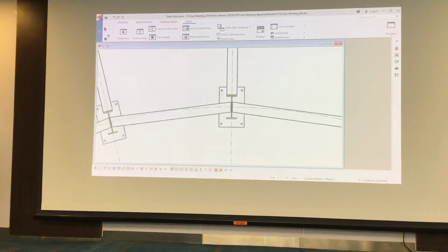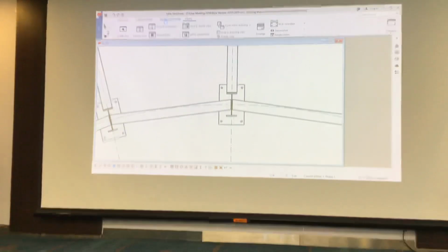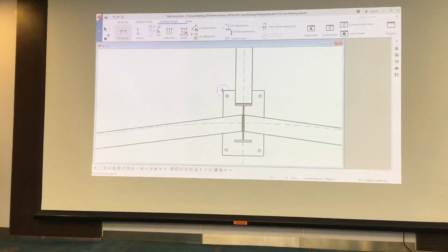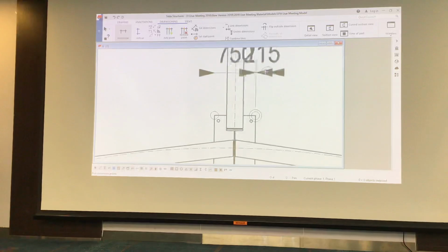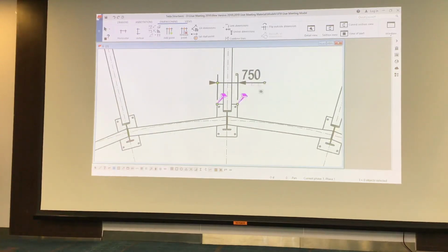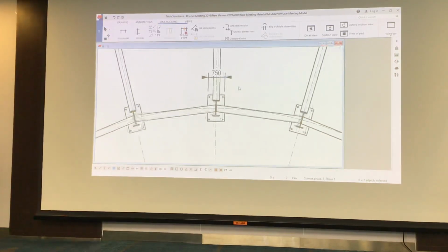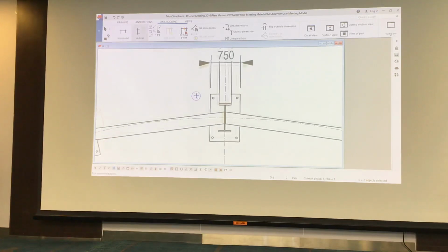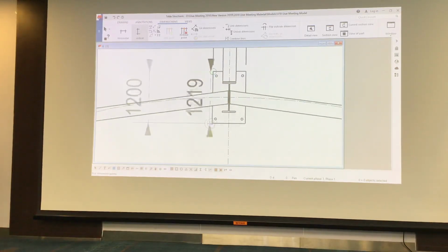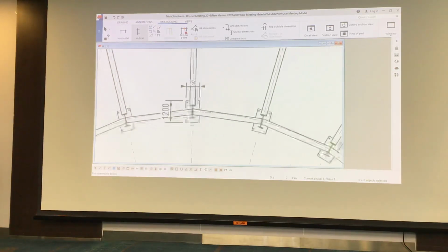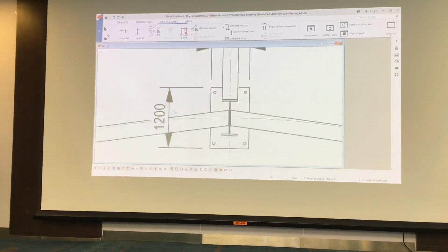So let's say I'm going to put some dimensions on this plate here. So I'm going to dimensioning, and I'll say, right, I want a dimension from this point here to this point here. I've added a dimension. I'll click on that mini toolbar. I'll say, actually, I'd like that to be 1.5, like so. So a nice, simple little dimension. Then I'll go to the vertical one here, and I'll say, right, give me this and this, a dimension like so, and I'll pick that one up. Where's my mini toolbar? There it is. Click on that, and I'll say, make those properties the same. So there you go. And I've copied the properties to be there.